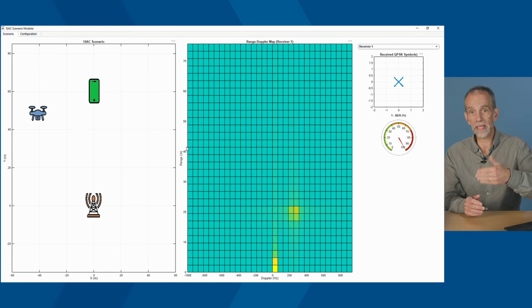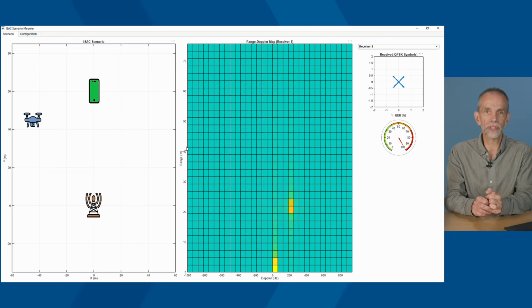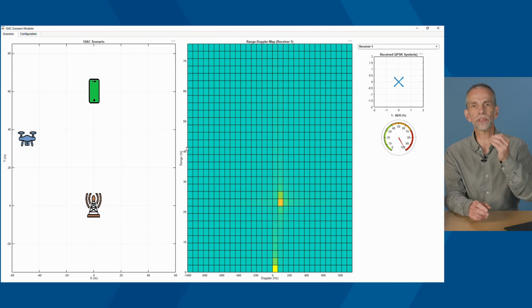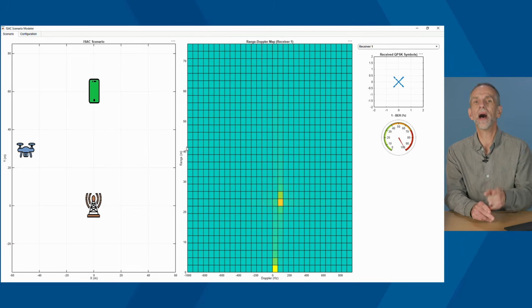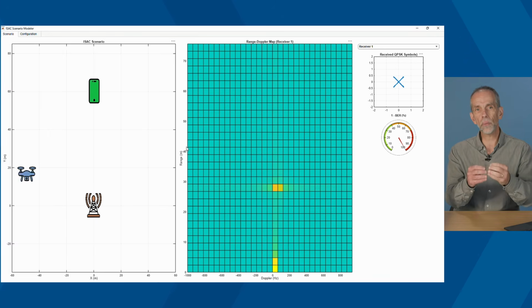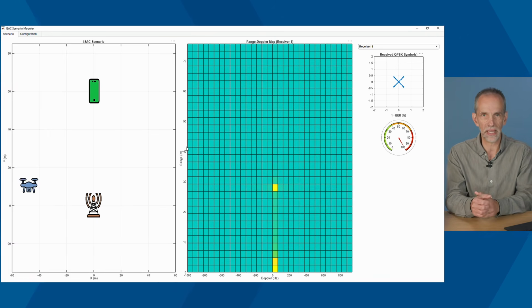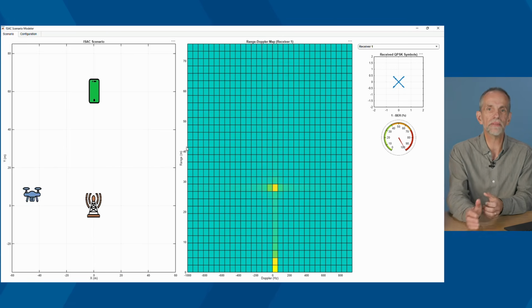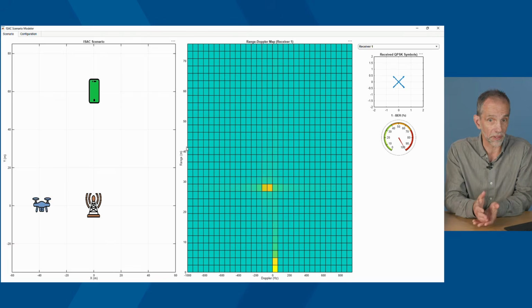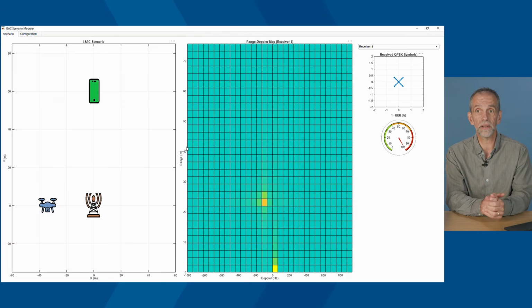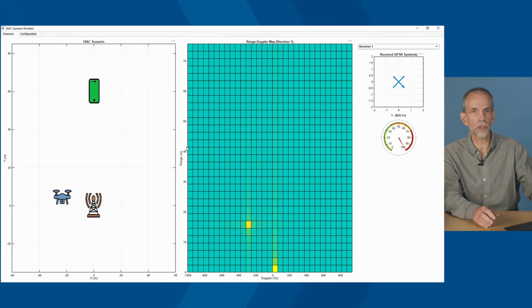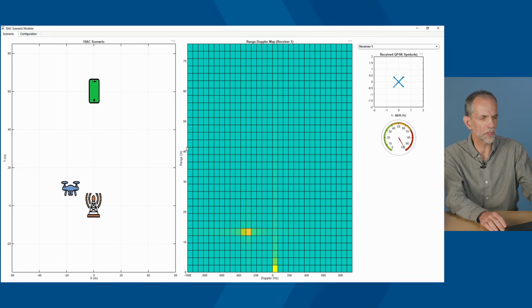And then with the concatenated channel estimates over time, we are noting that these channel estimates are evolving over time. That tells us what kind of Doppler is happening. When we do a forward FFT across these evolving channel estimates, we can get an estimate of the Doppler. And so it's actually very, very straightforward. In fact, I'm going to show you ever so briefly the code used to do this.